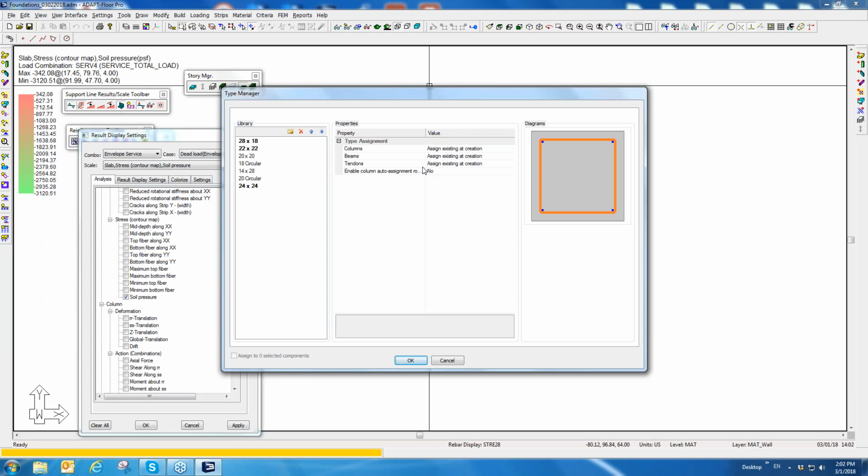So in essence, what we're going to add to the program is a beam manager where the program will auto detect beams that you've modeled. The user can then input a flange width, or you can impose effective flange calculations per code. The finite element solution will be used for the forces in that beam, but the beam itself will be designed independently inside of that beam manager, as separate from the strip design for just the floor or the level that you're working on. So those improvements are in queue right now.